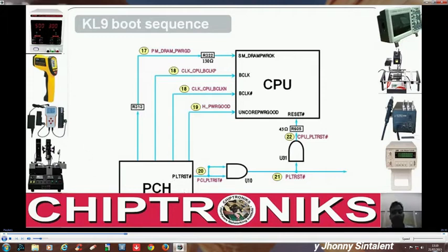And there is a very important question: how does this clock generator inside the PCH operate? Where does it get inputs from? There is a management engine BIOS, AMI BIOS in the SPI BIOS. It's the job of the management engine BIOS to initialize these clock generators, and I'll discuss this AMI BIOS inside the SPI BIOS, which is very important.